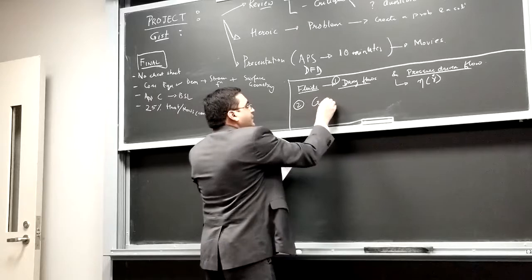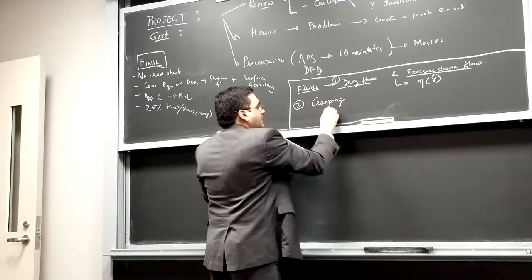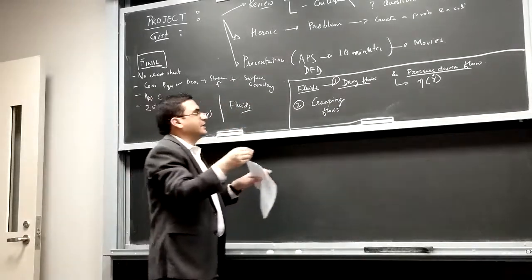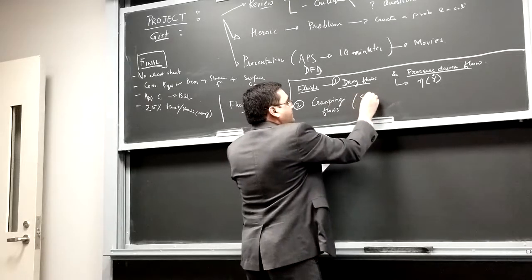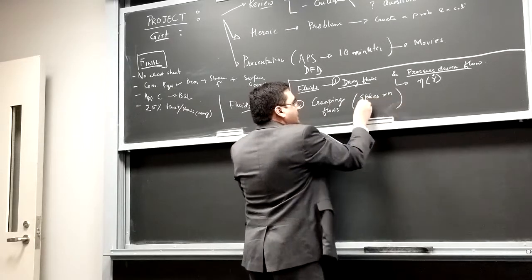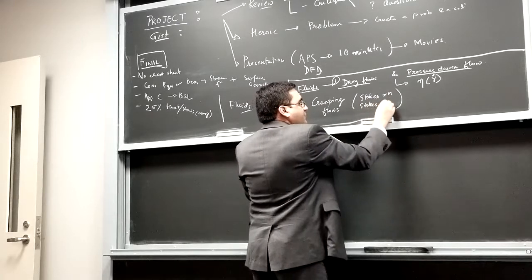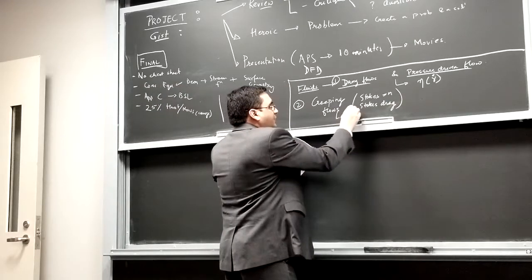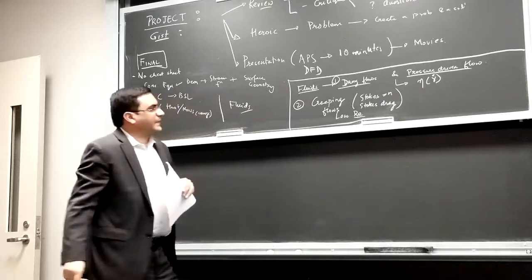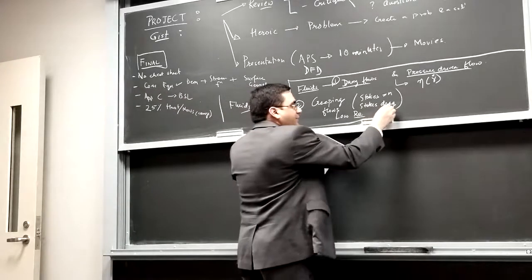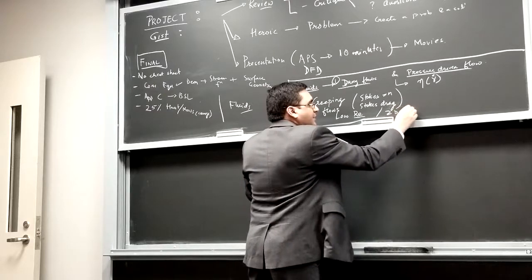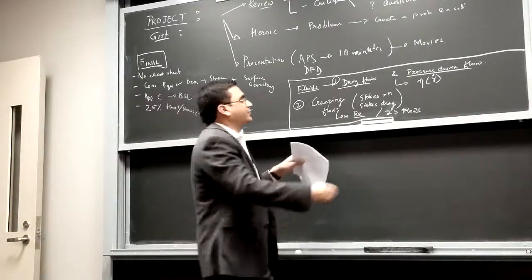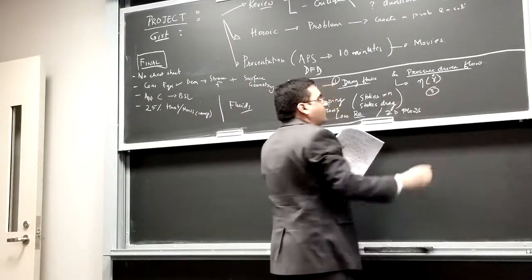Then we've looked at creeping flows. In creeping flows, we mainly looked at two examples, and you'll have some homework problems. Both of them involve Stokes' equation, and we also had some discussion of Stokes' drag. That's very important in the context of low Reynolds number hydrodynamics, and in this context, you also learn how to solve for 2D flows, both planar and axisymmetric. And we'll see an example or two more where the stream function formulation is used.